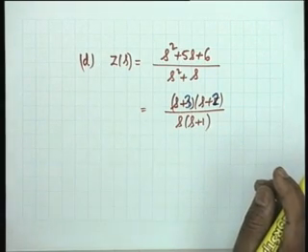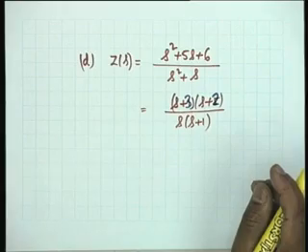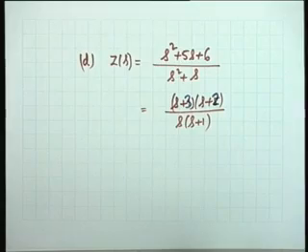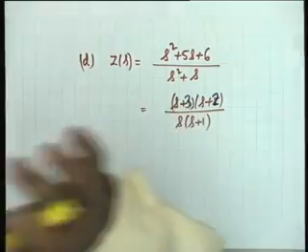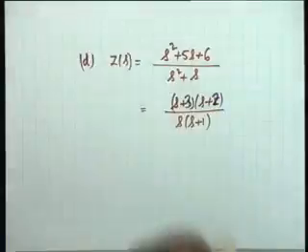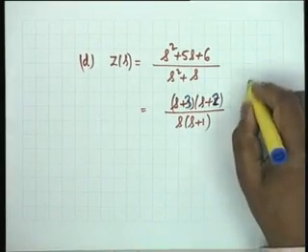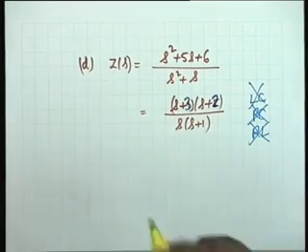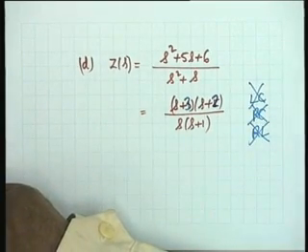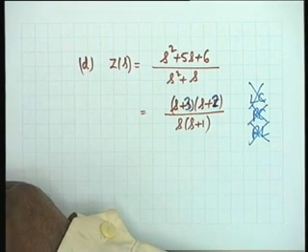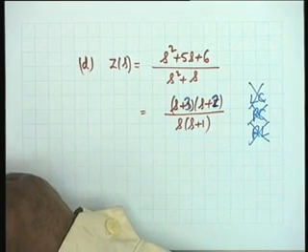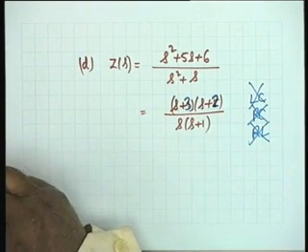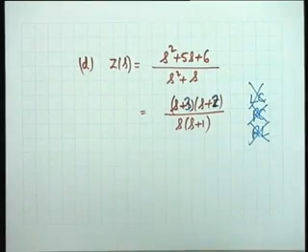So what is the conclusion? Whether it is RC or RL, poles and zeros must alternate. They do not alternate, so it is not LC, it is not RC, it is not RL. Can you say that it is not realizable? No, you cannot say, because it could be RLC. How do you determine whether it is RLC or not? Whether it is realizable or not? Give me one test which will determine.